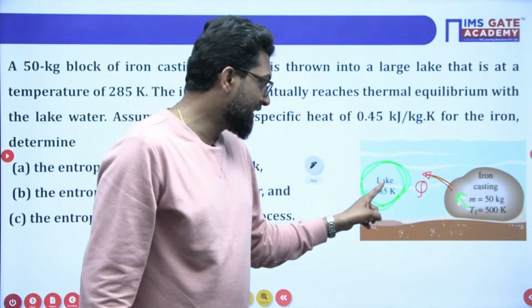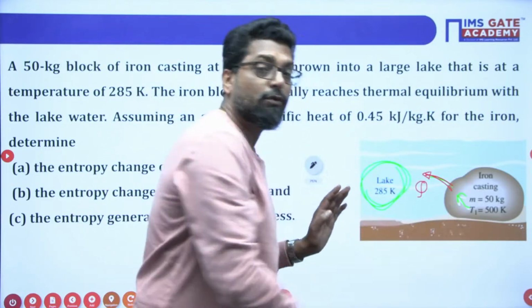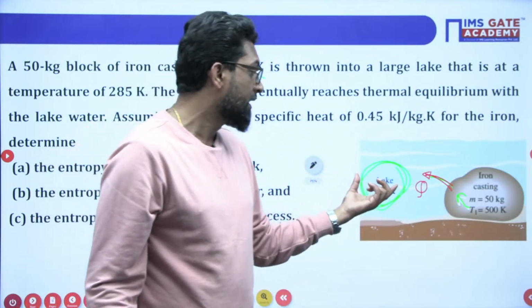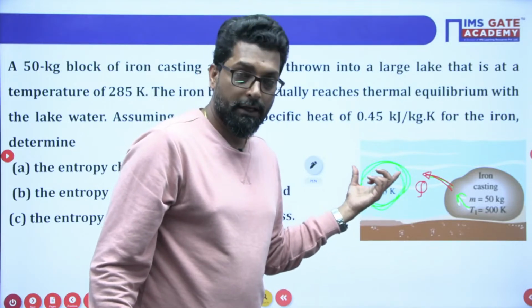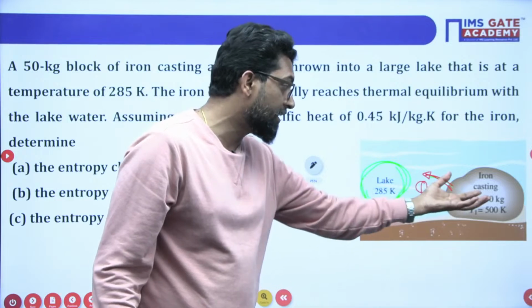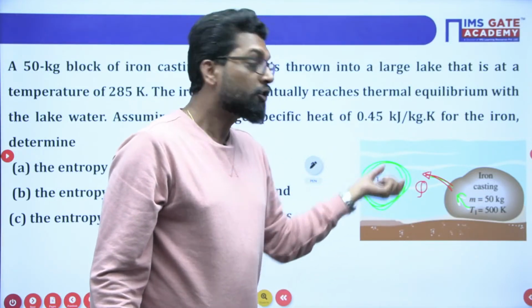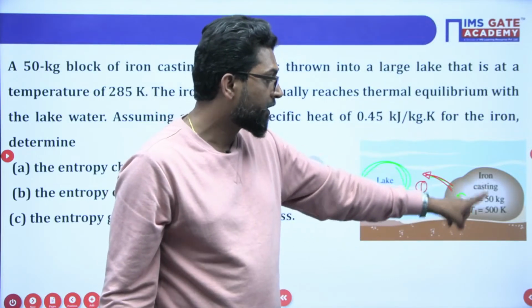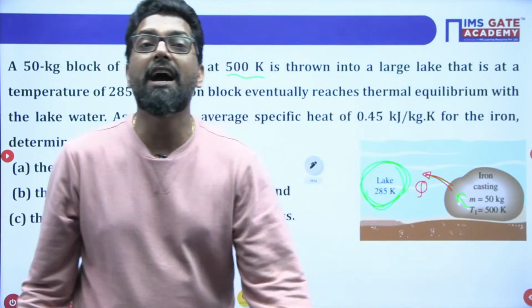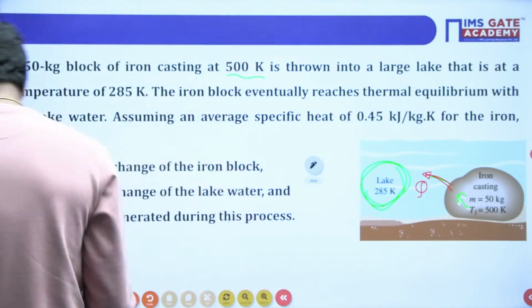But in this case, the lake as a reservoir has a very large quantity of water. It has a very large heat storage capacity. So, whatever heat is released by the iron, the temperature of the lake doesn't change. So, the final temperature of the iron is equal to 285 Kelvin. Okay.